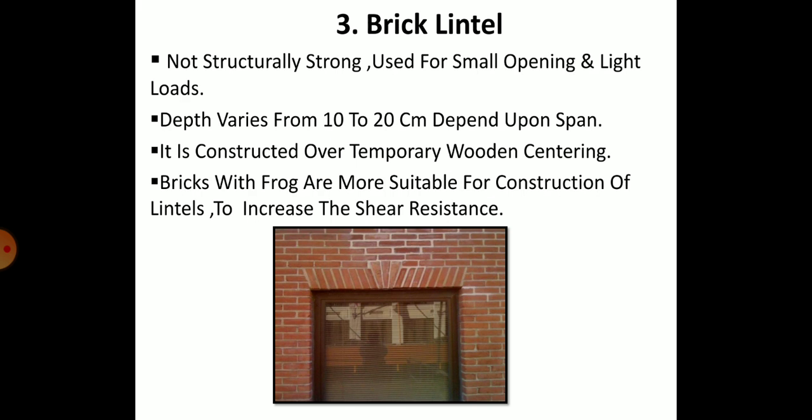The next is the brick lintel. Brick lintels are not structurally strong and they are used only when the opening is small and loads are light. Brick lintels generally consist of bricks which are normally laid on end and occasionally on edge. You can see here an image of the brick lintel. Mostly the depth of the brick lintel varies from 10 to 20 centimeters, depending upon the span. It is constructed over temporary wooden centering.